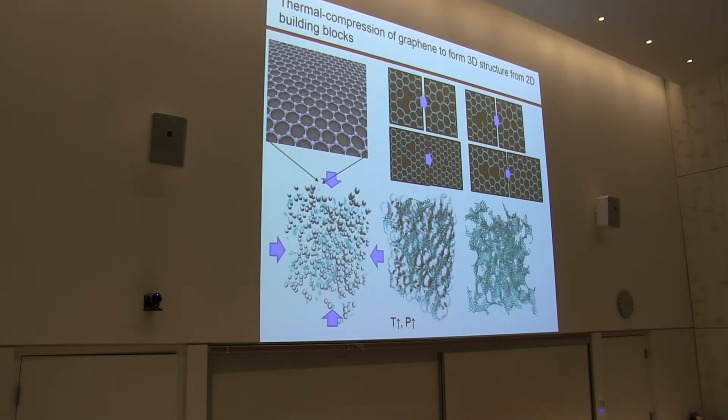The high temperature breaks those covalent bonds, and the pressure allows the covalent bonds to reform between those graphene flakes. At the beginning, there are a lot of defects. But once I repeat this cycle and do the annealing process for many cycles, those dislocations can merge or migrate to form 5-7 ring dislocations instead of big holes. So they can get an integrated structure after this kind of thermal compression process.